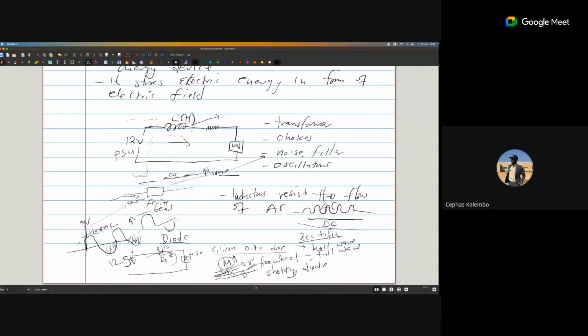Now, these cells are getting sunlight and converting it to electricity. How then do you collect that electricity so that it is usable? You can find, for instance, that this particular cell is just giving you 0.5 volts. So you want to connect this cell in series with that cell. This connection here is called a finger. This cell and that cell are connected by a finger. Then that will be connected with another finger, and that with another finger, like that.